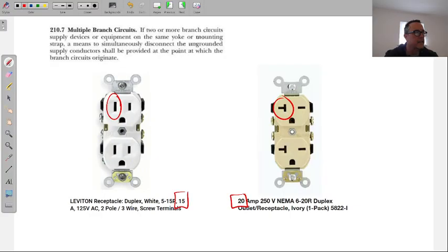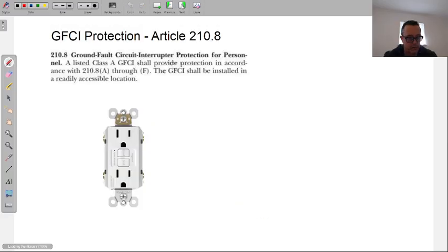Again, these are things that newer electricians should be able to point out, obviously as you're getting better and more school time. If I asked you for a receptacle and you know where we're going, and you know it's supposed to be 20 amps, these are all connections that we should be making. So when we see this GFCI, we should already identify it because of the neutral side being that configuration. This is a 15 amp rated GFCI.